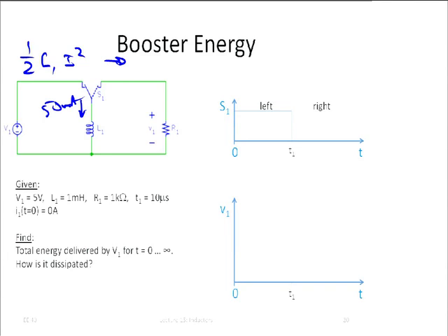That's what we want from a circuit. Remember, early on, we have some high voltage, and we want to drop it for some circuit. Let's say we have 110 volts. We want to drop it to 10 volts or so in order to power a circuit without blowing it up. How did you do that? Well, with a voltage divider. Was that thing also efficient? Well, hell no, right? It dissipated most of the power and very little went to the load. So if you use inductors instead, the picture is quite different.